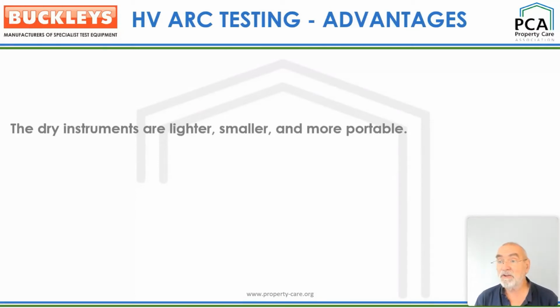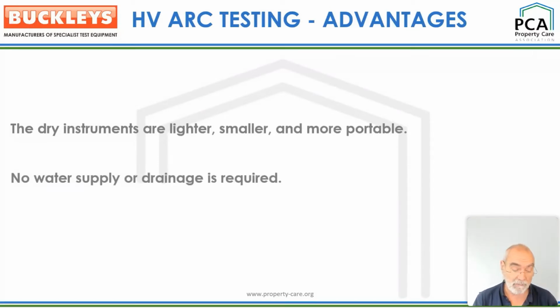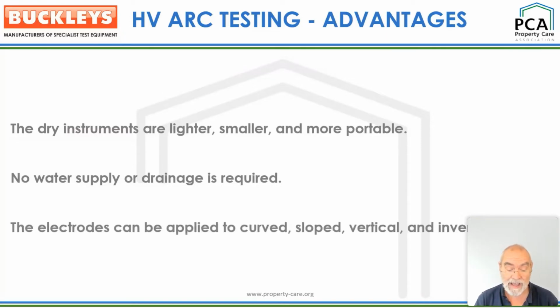Trying to keep a large, flat, possibly windswept, air and sun-baked roof wet would be extremely difficult in hot and dry climates. Even in the UK, in summer conditions, this can make the wet approach difficult, and the dry method is clearly preferable once the dew has evaporated. Couple this with the convenience and portability of a dry roof pro tester, and it's the go-to choice for many inspectors.